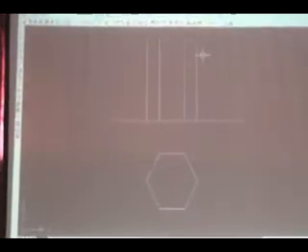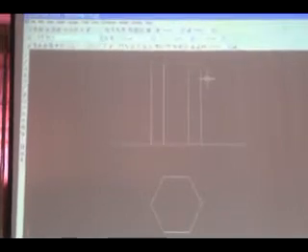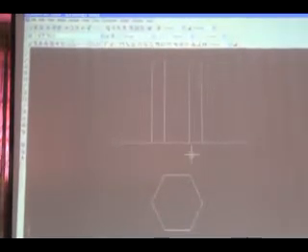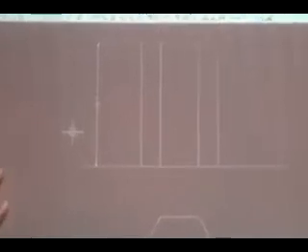This is just a drafting package. I can draw two-dimensional drawings in this, the same way you draw manually. Suppose I want to dimension it directly, you see this icon, it's a linear dimension. I am dimensioning from here to here. It shows the value of the dimension, and the extension portion, wherever you want to keep your dimension, you can.